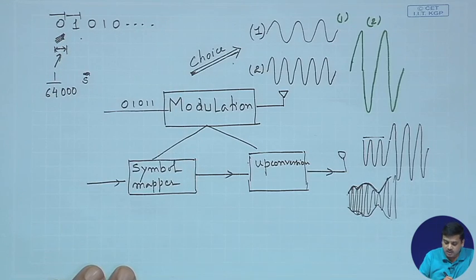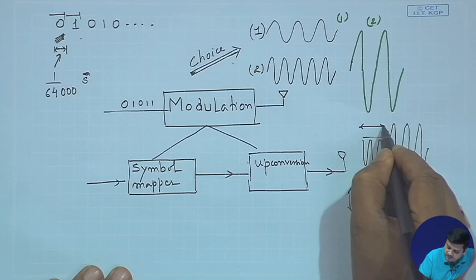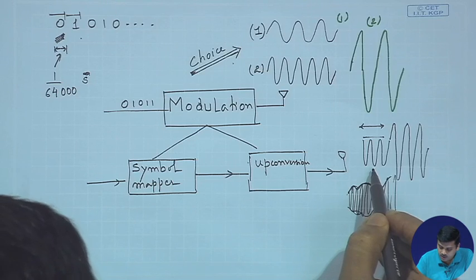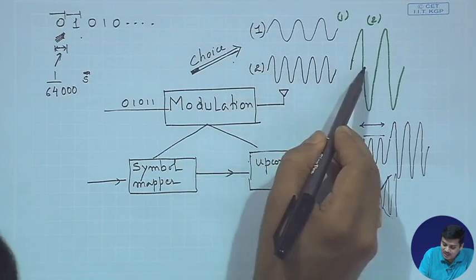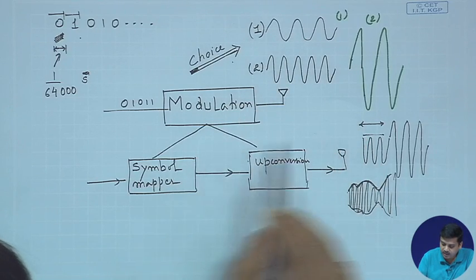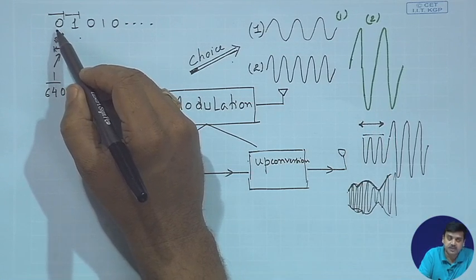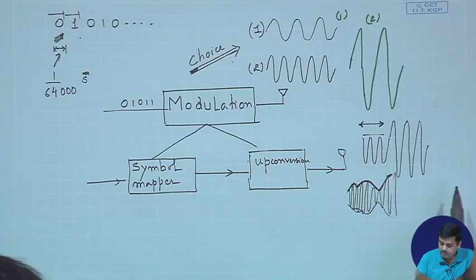Next instant there is another bit. So, the moment this information bearing signal changes, there is a change over here. All we are trying to say is that there is a finite, fixed duration involved with the existence or the choice of a particular waveform. So, there are two distinct differences that we see. One is that we are selecting between possible analog waveforms, and the second, these waveforms are chosen for a particular duration of time in correspondence with the rate at which bits come in, which is distinctly different from the continuum set of amplitudes or values, be it in time or in amplitude or frequency or phase that you get to choose, and also there is a continuity in time, whereas there is discreteness here in both the selected values as well as the duration over which this choice remains.